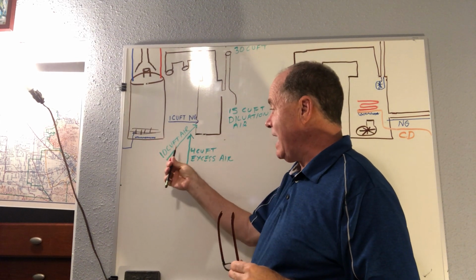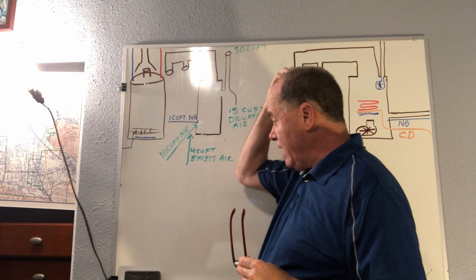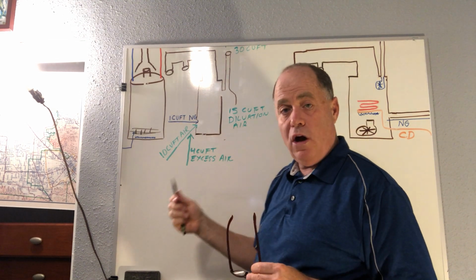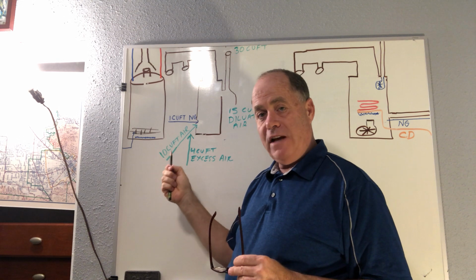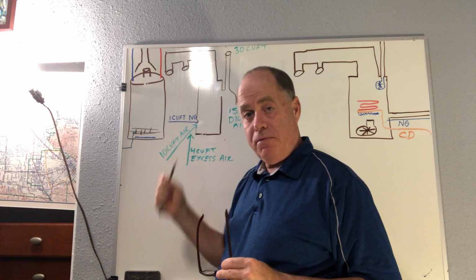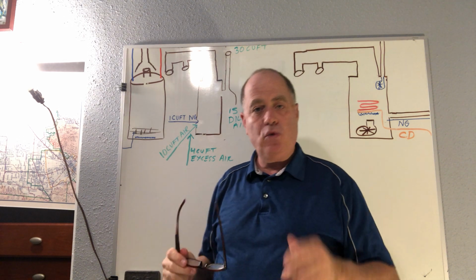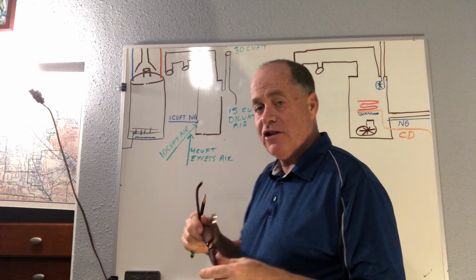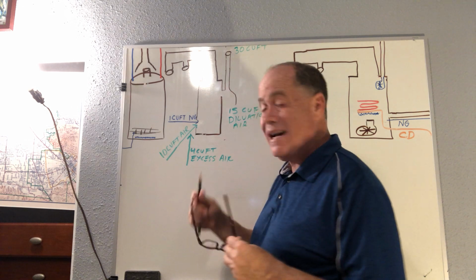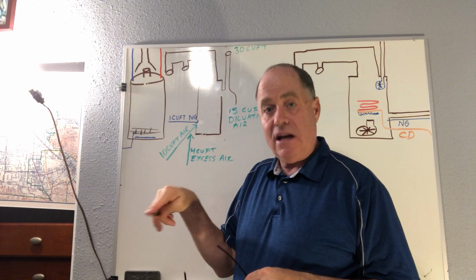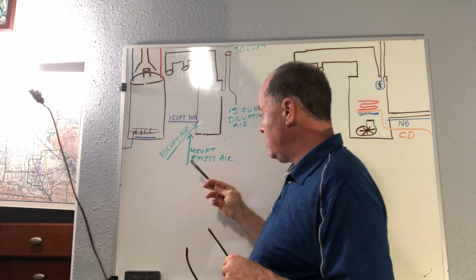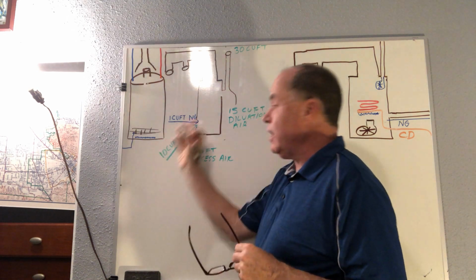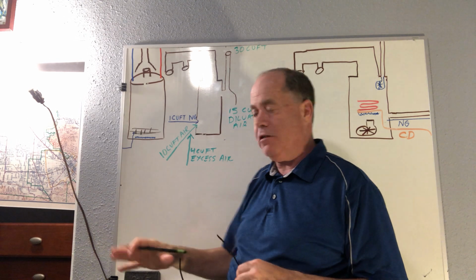So if you think of that, here you would have 2 cubic feet of oxygen mixed with 1 cubic foot of natural gas burning purely, right? Even when you go to light a torch, you have pure oxygen mixing with acetylene. So it's the oxygen and the natural gas, and you can see that you need twice as much oxygen as natural gas for proper combustion. We're also getting 4 extra cubic feet of air, excess air, to help move things along and make sure we have plenty of it.